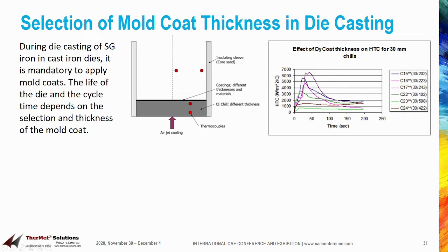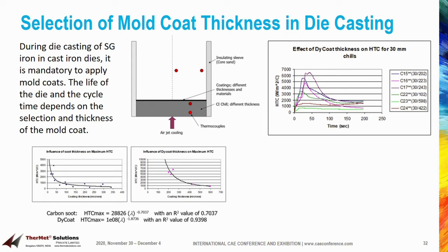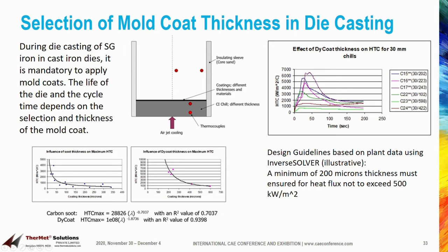In a case referred to, a series of experiments were conducted to collect thermal data with different coating materials and thicknesses. Design guidelines were developed on the basis of the heat flux at the metal mold interface, which were obtained by running an inverse solver.